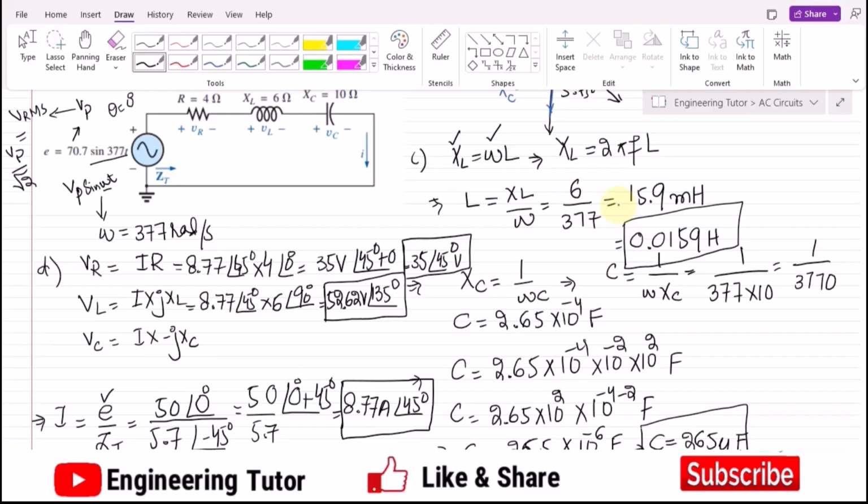So this is the V of L, and now the value of V of C is 8.77, angle again 45 degrees, multiplied by the value of minus j X of C. Converting them into the polar form, the magnitude will be 10, and the phase angle it has will be minus 90 degrees.